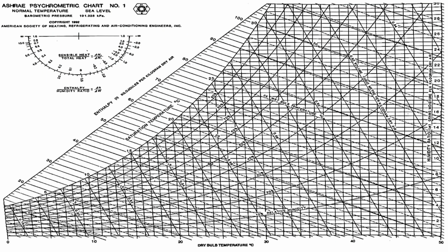Ambient is at 34 degrees Celsius, which is this line, crossing with 55% relative humidity. So we can take directly the omega value and H value. The second point is the room inlet temperature at 28 degrees Celsius and 50% relative humidity. For the hydronic system with desiccant, we have the desiccant first, following the adiabatic dehumidification line, which is parallel to this dotted line. Then we have the chiller or the cooling coil, which is a horizontal line. So we can extract the enthalpy data.